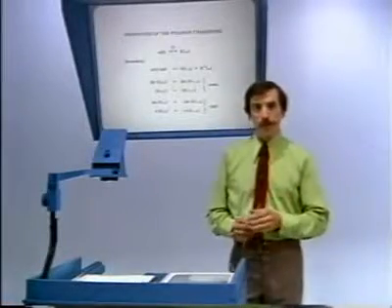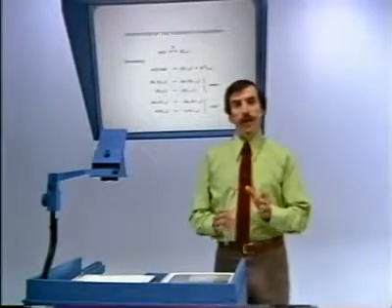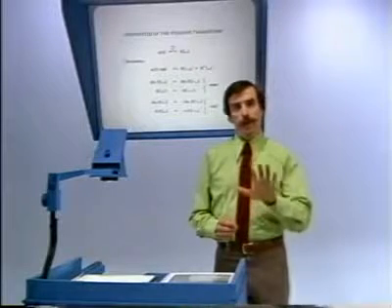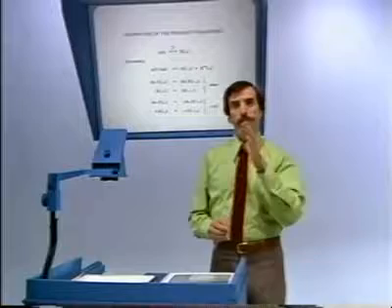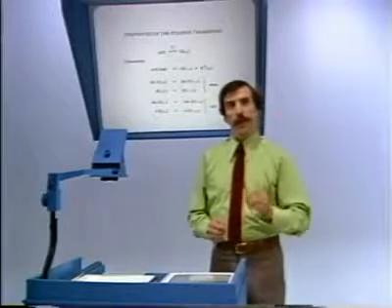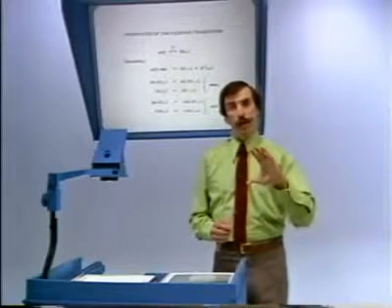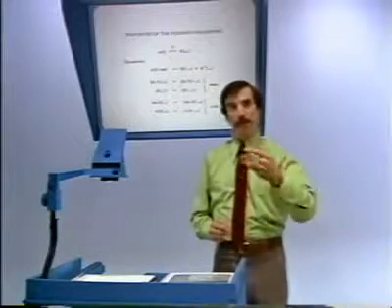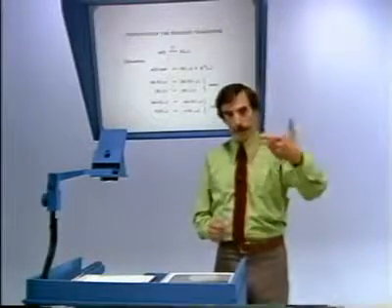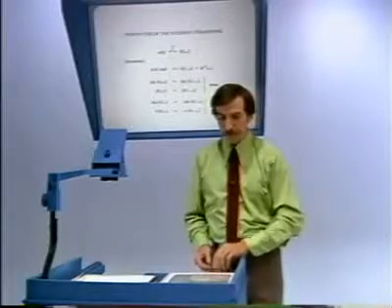So we have this symmetry relationship that for x of t real, if we think of either the real part or the magnitude of the Fourier transform, it's even symmetric. And the imaginary part or the phase angle, either one, is odd symmetric. In other words, if we flip it, we multiply by a minus sign.